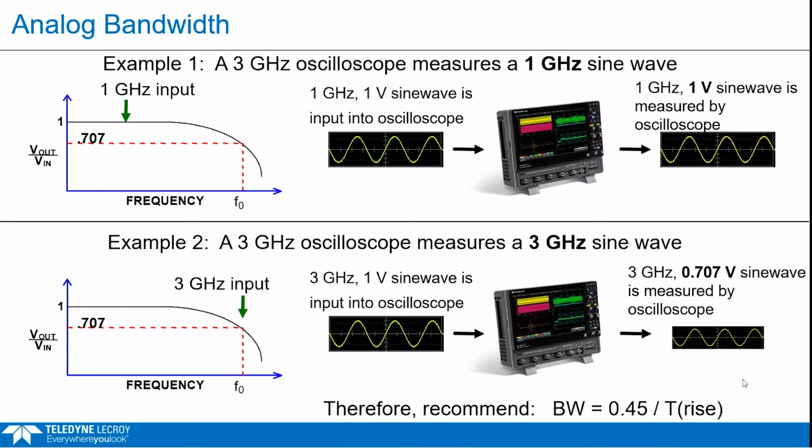But most important, back to the amplitude versus frequency roll-off. You know, get a scope that has higher frequency. If you're not pushing the limits of the scope with the frequency content of your signal, no problem. If you don't care about the amplitude accuracy, you just want to see a signal, then this is not an issue as much, right?